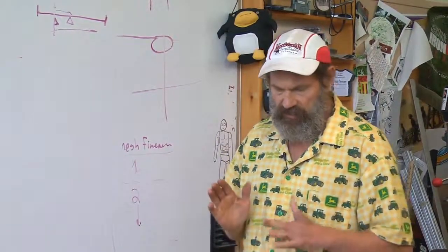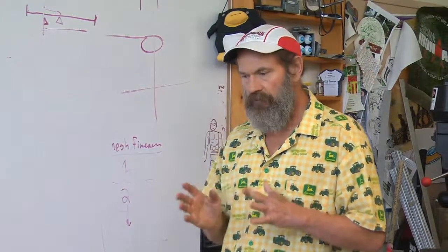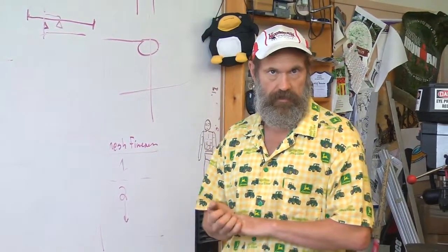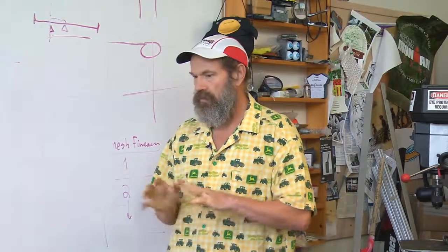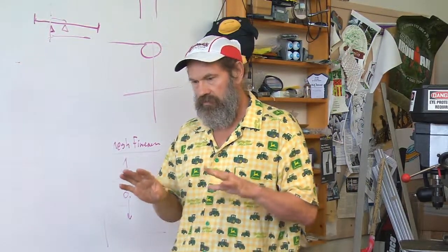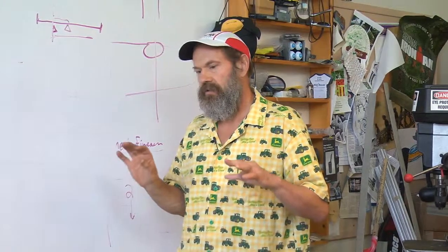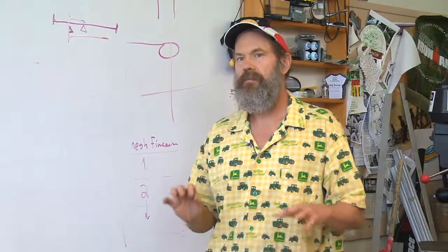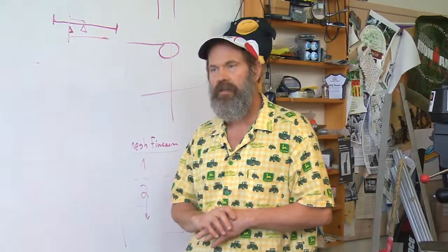Remember, whenever you have a sudden change in something, it's often good to remove material and put in a nice gentle fillet to prevent that stress concentration. Okay? Now, let's go to the remaining topics of how do we minimize the weight while maximizing stiffness and strength.